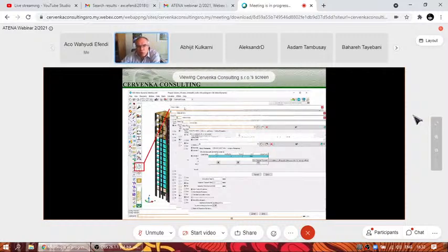For instance, in my case here, in the first interval, I defined boundary conditions and maybe also some fixed contact conditions. And now in all the other intervals, I can just say, okay, use the data from interval 1 with maybe multiplier 0, because I don't want to multiply them by anything. They are just supports. And I can then reuse them.